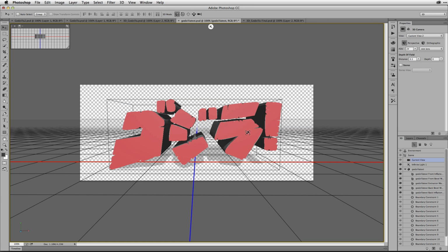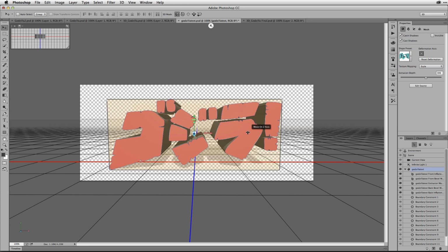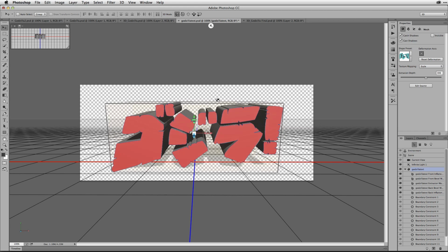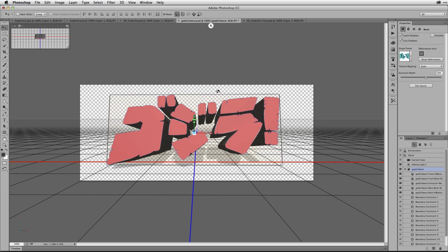And you'll start to understand the difference between the two. Okay, in this case, I want to do a slight rotation. I'm going to select the object as you see here. Then move to the edge of the object and notice that the icon changes over each surface that you pass over. So if I move to this position, I should be able to rotate it. Did you see the icon change? Now that shows you how easy this is.